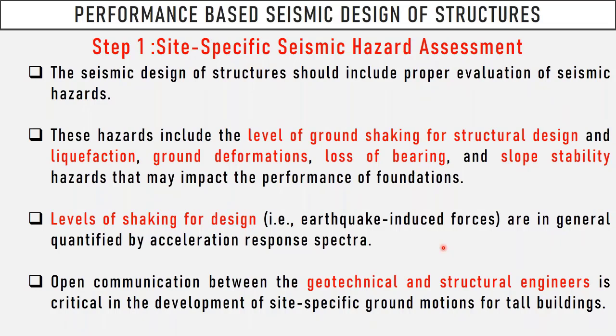Just to wrap up what is done step by step in a performance-based design of a tall buildings process, of course, you do not use the codified hazard maps. You need a site-specific hazard assessment performed specifically for the location, considering all geological and geotechnical aspects like liquefaction, ground deformation, slope stability, and so forth. And of course, levels of shaking that you are going to use in the design.